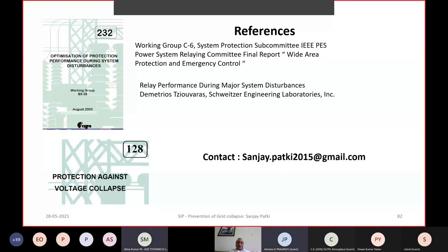Yes, hello. Sir, you have mentioned the restraint quality during inrush condition. I have a question. Suppose there is an old transformer, and the inrush current is maybe 6 to 7% of the full load current, or suppose the inrush current is 10%. Then how will it protect? Or suppose the transformer is already faulty and then inrush current is also there. So there is a possibility of damage to the insulation, sir.